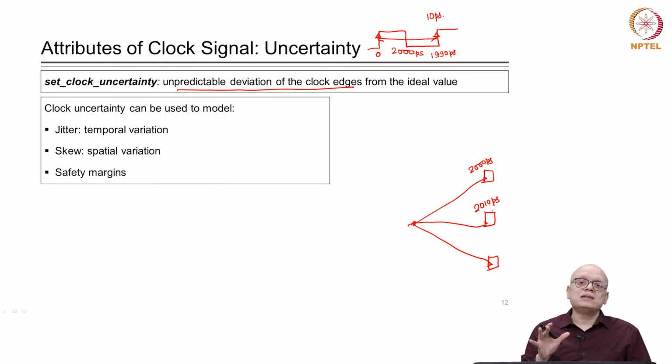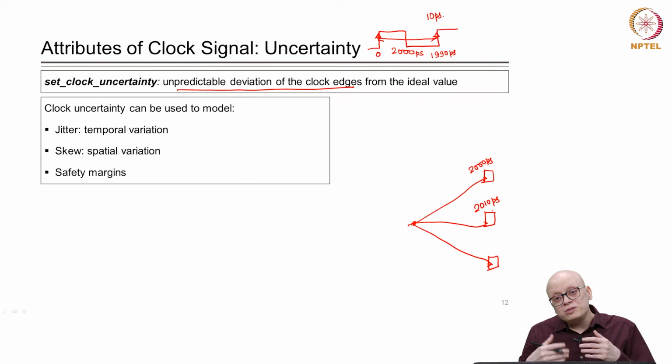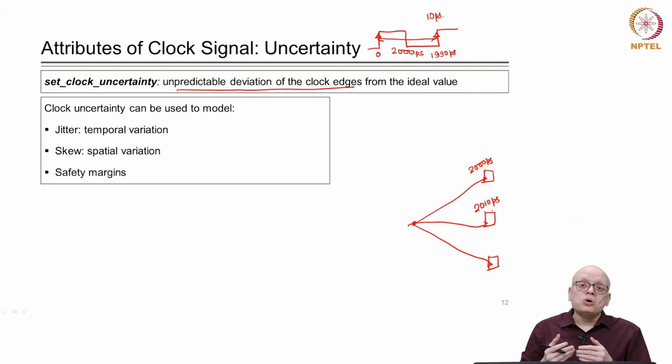So, if we do not give any uncertainty in the logic synthesis, then the wire delay can be assumed as 0, and the timing will be met very easily, and the tool may not be doing sufficient timing optimization such that the timing of our circuit is met.